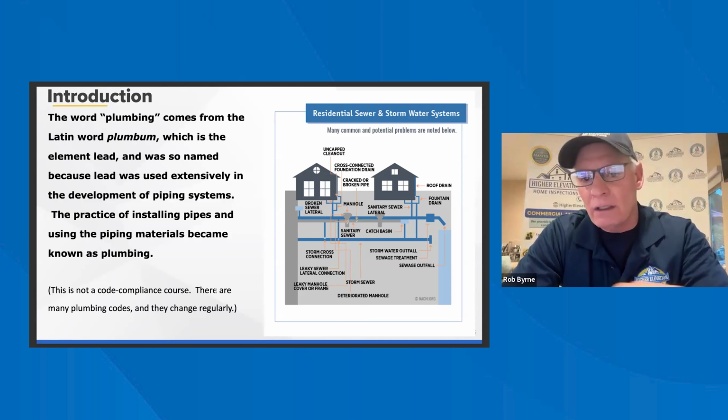Should not be threaded on the bottom. If it is, I highly recommend calling it out. Again, you got the pressure relief discharge tube. That's pretty much the safety mechanism for the TPR. You have it on the boiler, you have it on the water heater. Let's see, it says 18 inches from the floor, but as long as you know that it should be lower to the floor.